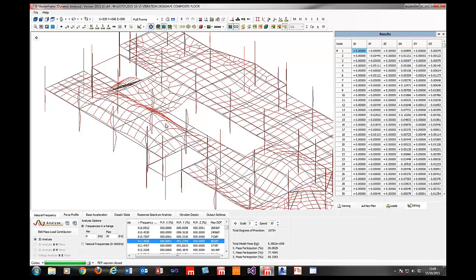The steady state is, if you like, a convenient way in that when we know the structure is going to operate or interact sinusoidally in a steady state fashion, then we can sum up the response, i.e. the acceleration, the root mean squared acceleration, using simple empirical rules.